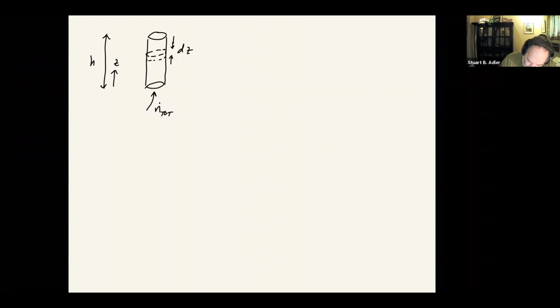And I'm going to define the pressure here. This is P1 max. So the maximum pressure is the pressure at the bottom, and then that pressure drops as the gas flows up. So if we think about just a material balance here, we can say that whatever flow of air you have at point z, if I look at the difference between that flow and the flow at z plus dz, that has to be the amount of material that is going through one of the cells.